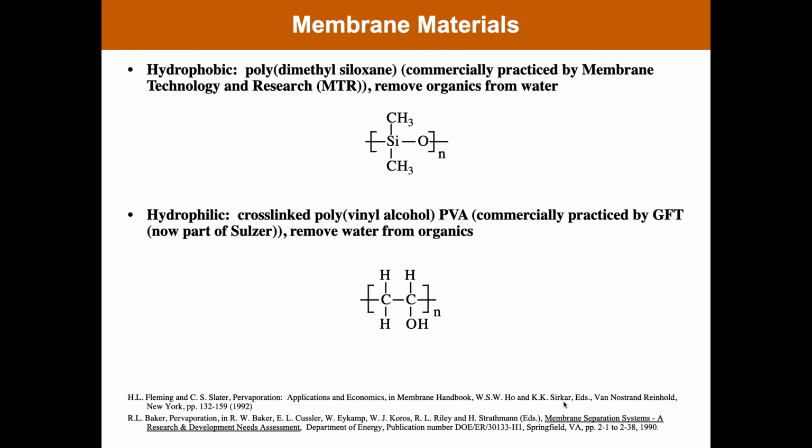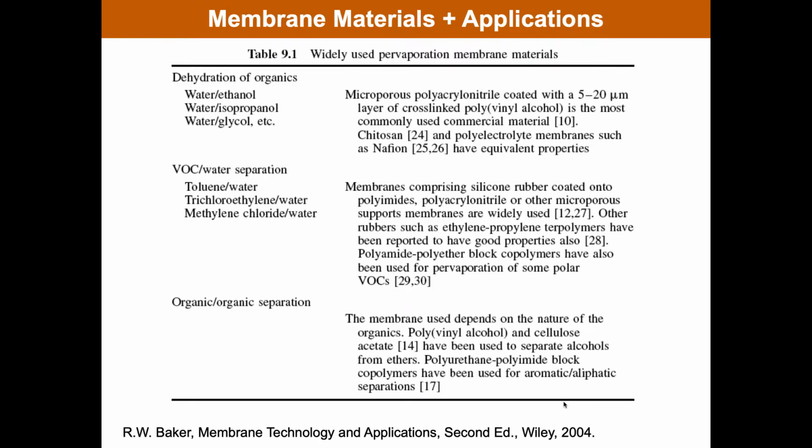For example, water is so much smaller than ethanol that even in traditional polymers like glassy polymers used in gas separation that might favor the solubility of the organic, the diffusion selectivity in favor of water is so great that things like polysulfone and polyimides and so forth are water selective in water alcohol separations, and they've been tried in some of those cases. But these are the ones that have the longest track record in the field.